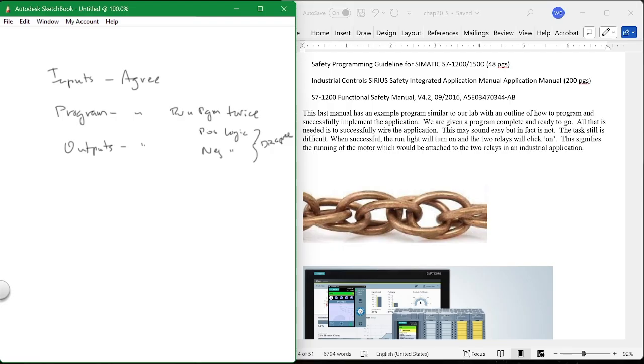So if it's straight logic, De Morgan will work. You follow me? If it's straight ANDs and ORs logic, De Morgan will work. You do it positive, you do it negative. They've got to disagree. If they don't disagree, you shut it down. But with timers and other things like that, you have more sophisticated logic. And honestly, I don't know how those work, but I do know that they do.